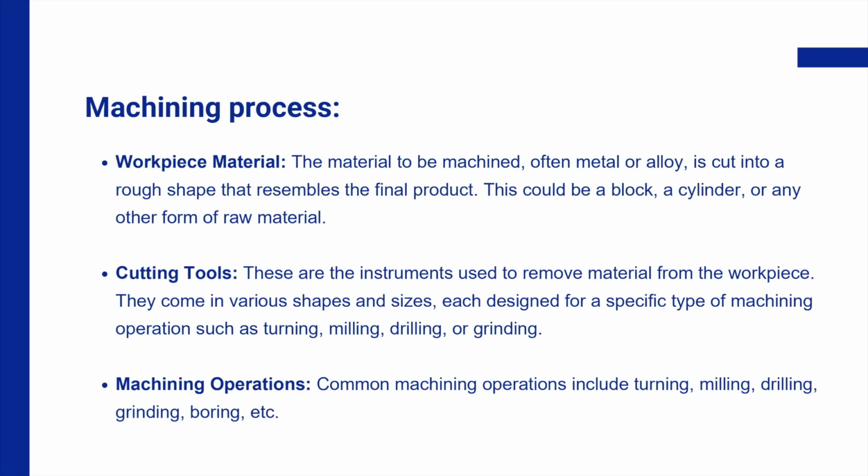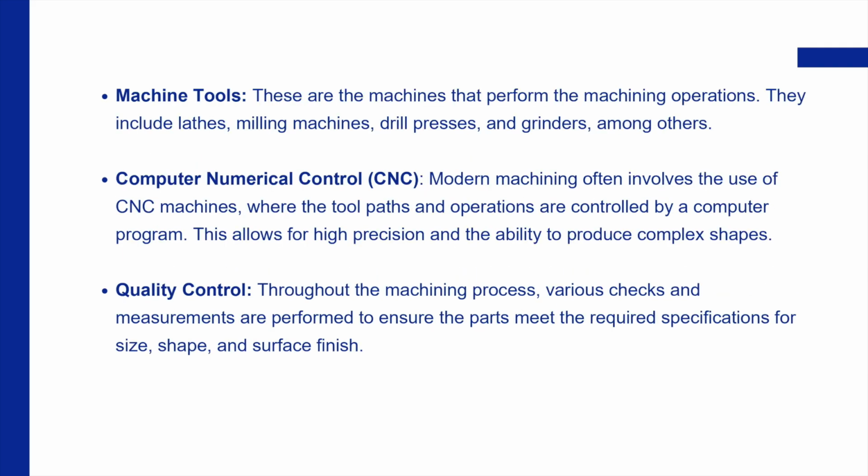The machining process usually follows a series of basic steps. First, the engineer selects the appropriate material and cutting tool, and then the workpiece is secured on the machine to prevent movement. Then the correct machine settings, such as the speed and the feed, are selected based on the material.